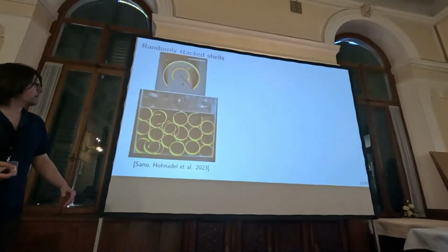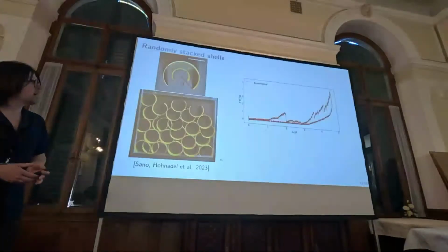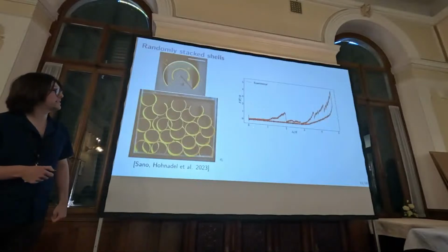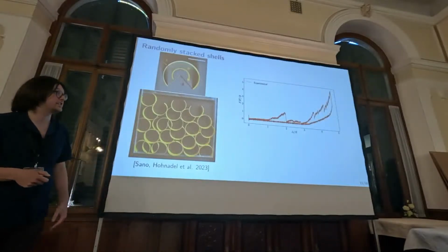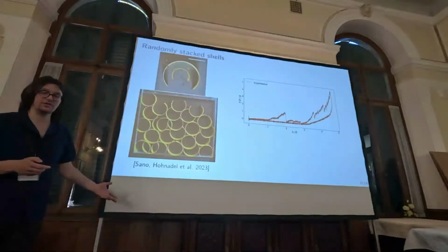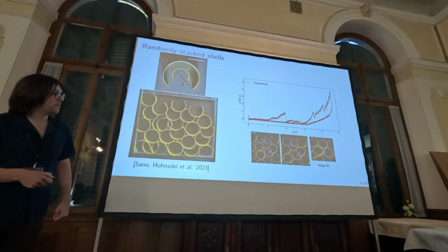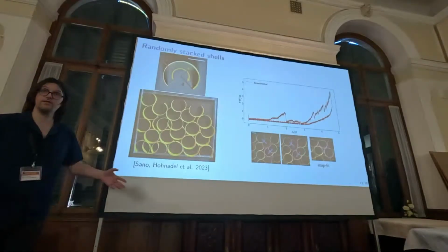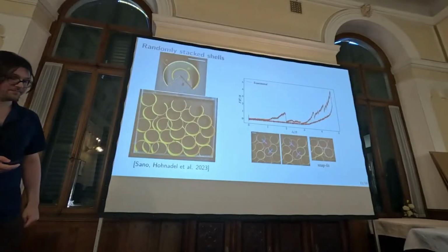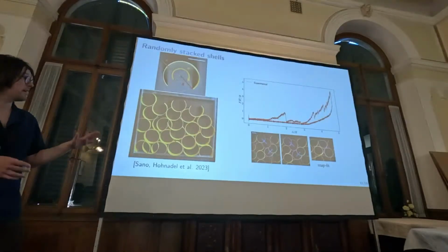And we can measure again a force displacement curve. The one obtained experimentally looks something like this. So we have a hysteresis curve, meaning we have dissipated energy. But what's more interesting maybe is the sudden jumps that occur regularly that are due to the snap fit effects. As we can see here, when the load is high enough, multiple rings can snap into one another, suddenly reducing the overall forces.